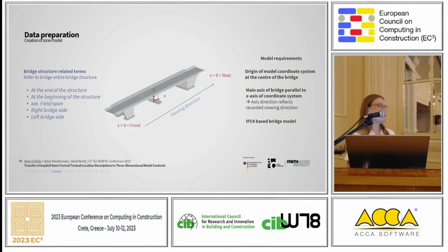And then finally, we have to align or rotate the model until it fits the outside recorded direction, like from city A to B. And we did this in this approach just manually inside the modeling software. I know there are automatic approaches for that, but at this stage, we just did this manually. And further, you can also say now that all positive y values refer to left and the negatives to right. And the z-axis, the vertical axis, is just going up.